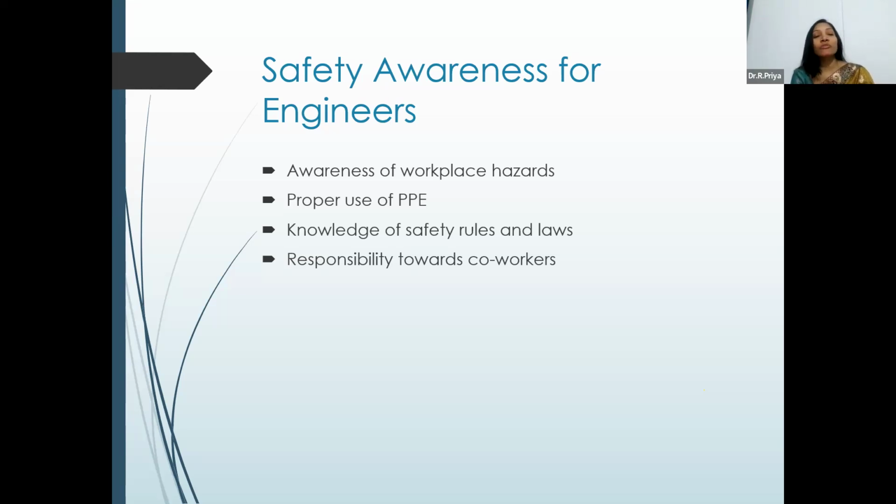Then a proper use of personal protective equipment. The engineers must not only wear the PPE themselves, but also ensure that workers use the correct PPE for each task, because the PPE acts as the last line of defense against hazards. During grinding or cutting operations, wearing safety gloves and a face shield protects the engineers from flying particles and eye injuries.